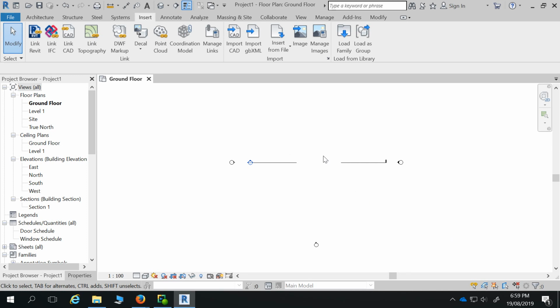I've just started up a new architectural template and I'm looking at the ground floor here. If I decided that I was going to set out something like this room with some desks and some chairs, rather than use the copy tool and add one desk and copy another and then do the same with the chairs, we could use the array tool to do a linear array. And in your case, you had one that was a radial array. In the last bit of that exercise, you arrayed, what did you array? Was it desks or something?